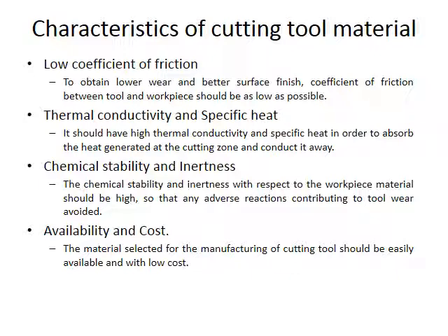And the last but one, chemical stability and inertness. The chemical stability and inertness with respect to the workpiece material should be high, so that any adverse reaction contributing to tool wear is avoided. That's why these are very important properties or characteristics.